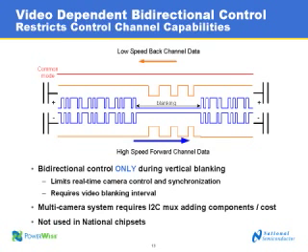And just a couple other comments. Some of the multi-camera systems require a separate I2C mux. This alludes to the comment we made earlier, where we have the ability to remap common addresses to unique addresses. A lot of the alternative solutions don't have this capability. So there's actually an additional device and additional cost associated with supporting multi-camera systems, if they take this approach. Exactly. And as we noted, this approach is not used in the National chipsets. We send everything continuously regardless of what's going on in the video.